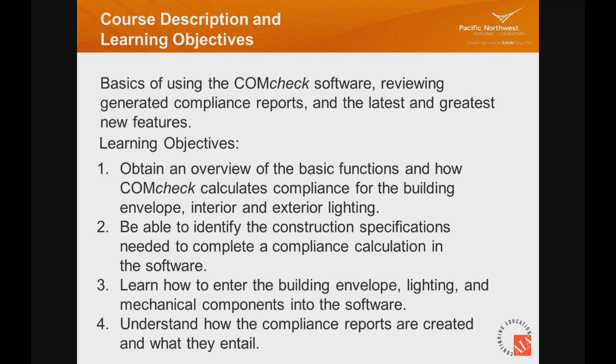So for COMcheck, the software itself, really for today's webinar, we're going to go over the basics of how COMcheck works. So we're going to give an overview of the basic functions and how COMcheck calculates compliance for the building envelope, for interior and exterior lighting, and then how mechanical systems and plants and service water heating can be entered into the program.